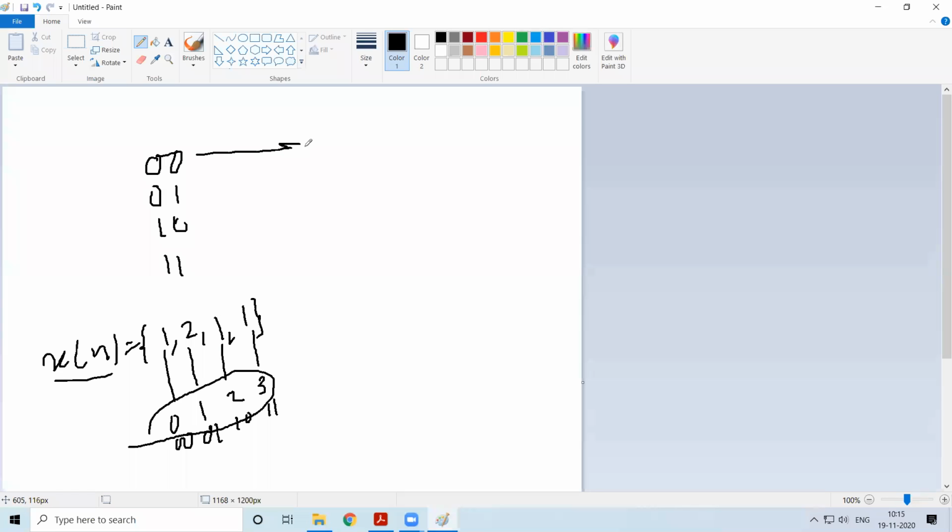Now in bit reverse, because in FFT, when we apply FFT, generally the outputs are in bit reversed form. Either the outputs you place in bit reversed form or the inputs you place in bit reversed form. These samples will be sitting over here: x of 0 will be here, x of 1, then x of 2, and x of 3. The values are 1, 2, 1, 1. So they'll be sitting in the memory locations in this form.